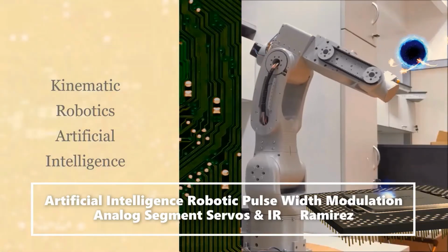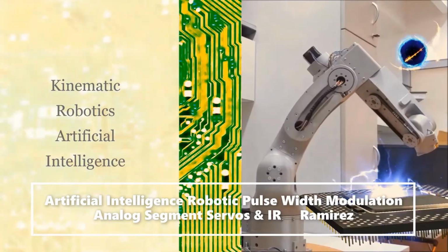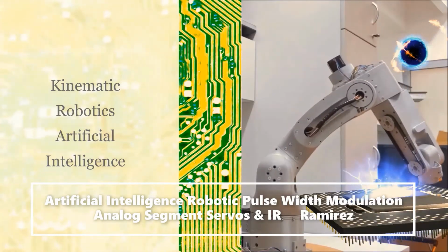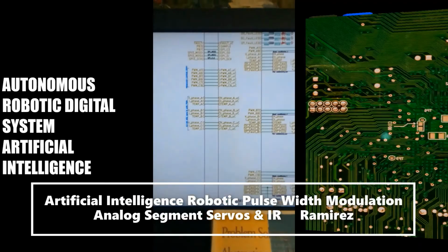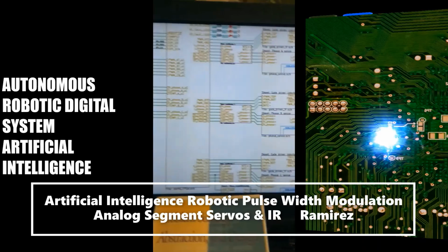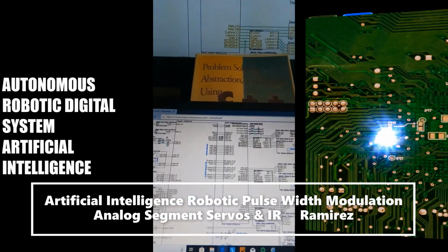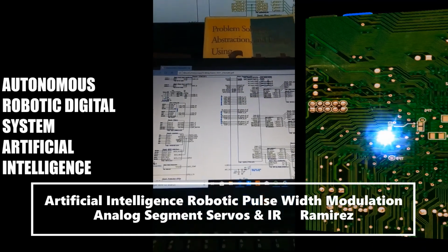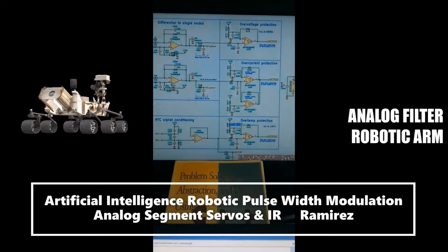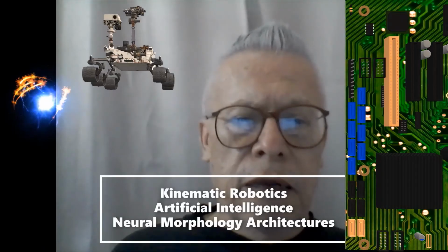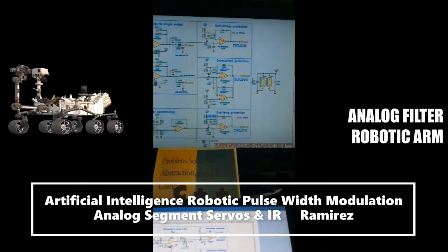The servos are powered by a 6 volt DC power supply by the adapter through the main digital section. The distance of the infrared sensor is measured by the position sensitive detector, which translates the measured distance through the IC of the sensor to an output voltage. The greater the output voltage, the shorter the distance.